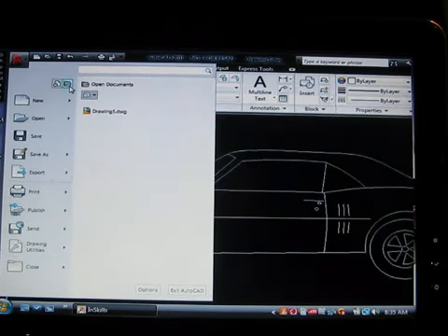Elsewhere, you have the Exit AutoCAD button at the bottom. I'm pretty sure it's obvious as to what that does, but it will shut down AutoCAD. If you haven't saved any of your files, don't worry, it will ask you if you want to save them. AutoCAD is very polite this way. The Options button will open up your Windows Options Setting Manager. This window is where you go to set and manage many, if not all, of your settings in AutoCAD.